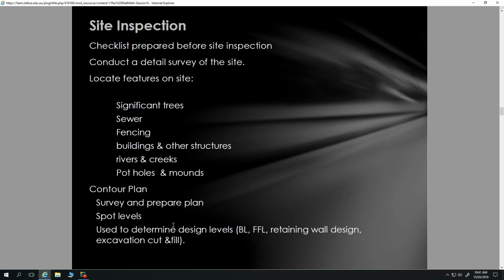The push rod goes into the ground, ram it down with the motorised ram, and then join another one on. Just keep going like that, and then set up a tripod above that with a winch, winch it back up, take a piece out, winch it back up, take a piece out, like that. So it could all be done in the hallway of a building. So that's a way of doing it in restricted areas.